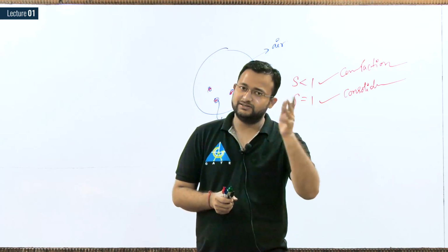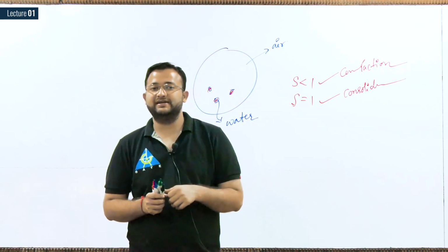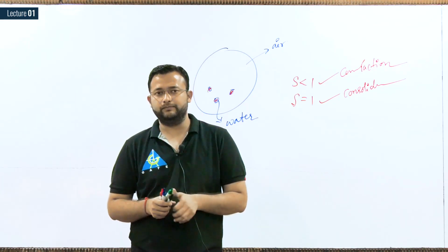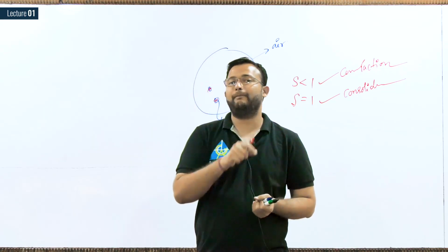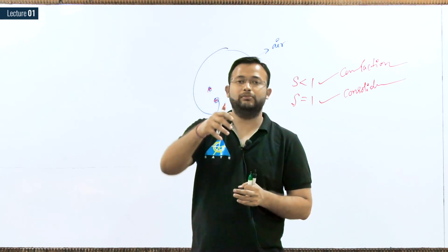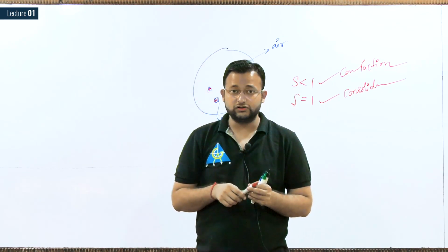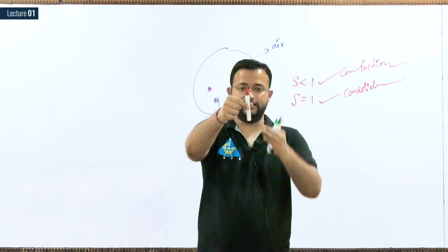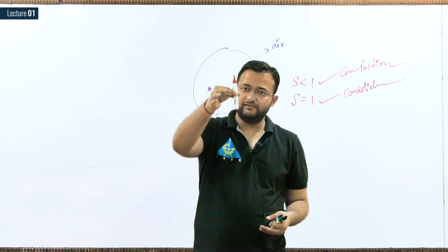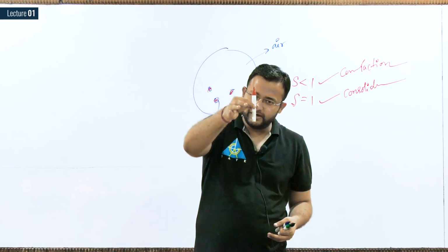But what will happen? You just think something. If the soil is highly compressible, means a number of voids are there, some voids are filled with air, some voids are filled with water. So what will happen if you don't compact your soil before the construction of any structure, directly you are constructing the building on the plot? Because of the self weight of the building, suppose this is the building, this is the height of the building, and I kept this building on any plot, on any soil. So because of the weight of this building, what will happen? Compaction process will happen. So the building gets settled.